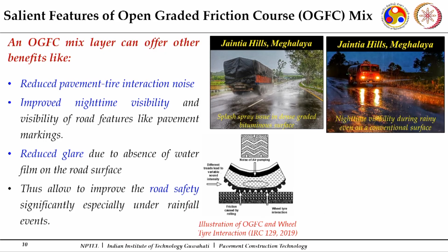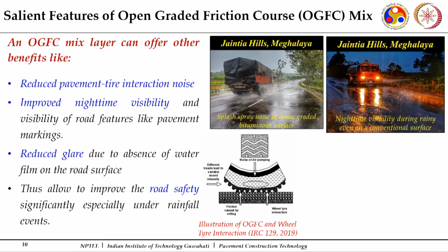So, some other salient advantages which these kinds of mixes normally offer are, you can see here a heavy vehicle, a good amount of splash and spray is generated because the water takes time to get removed from the surface. And during night time, when the water film is there, a lot of glare is also produced, and this presence of water film and glare even brings challenges to see your pavement markings or roadside features also. So, the visibility gets impacted when this water film is there.